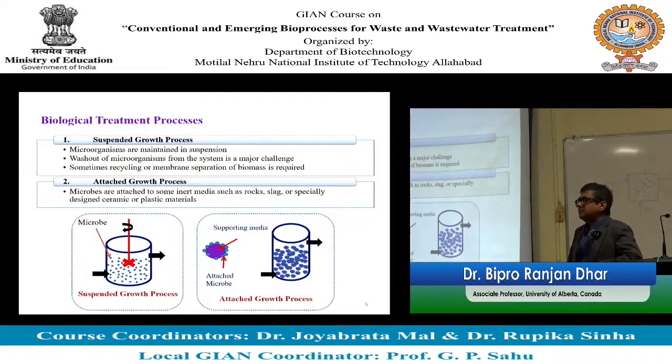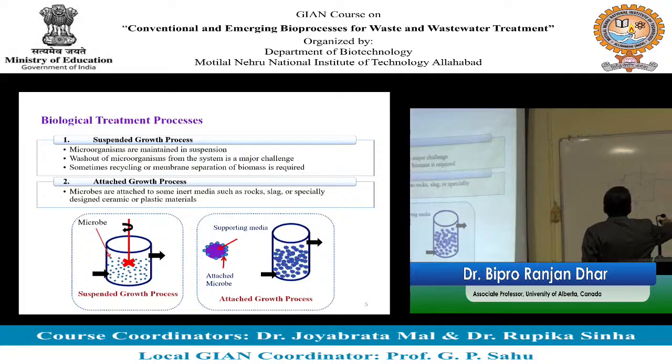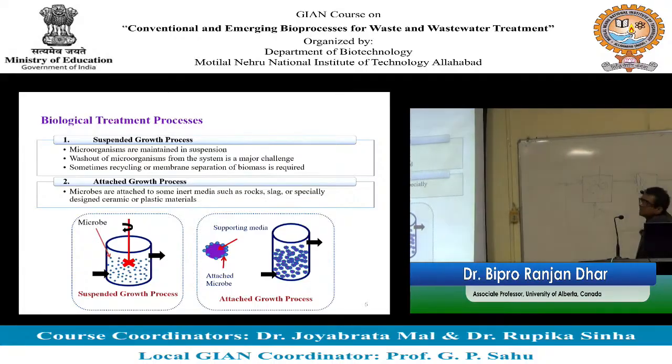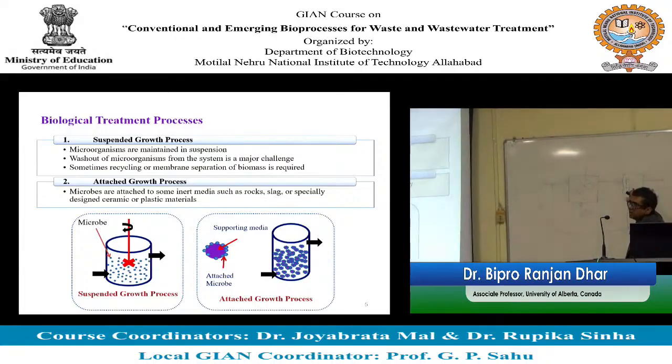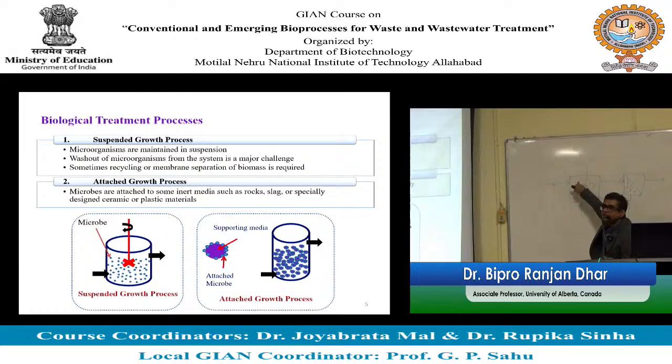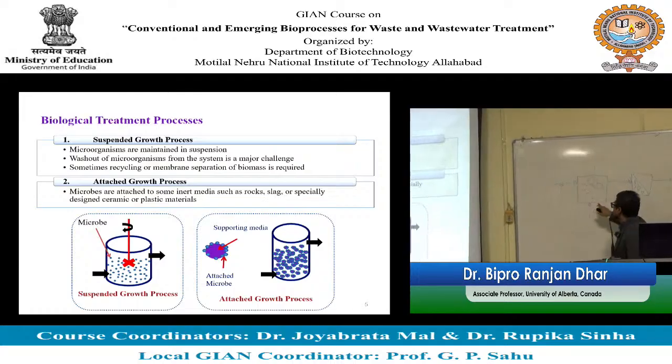So ultimately sludge will be settled in the bottom, right? Even with the installed membrane. Here we showed that it's a separate unit, and sludge is going to be retained in the system, okay. But yes, instead of outside, you can put the membrane unit inside, okay. But in that case, you still have to directly waste some sludge from the reactor, okay.